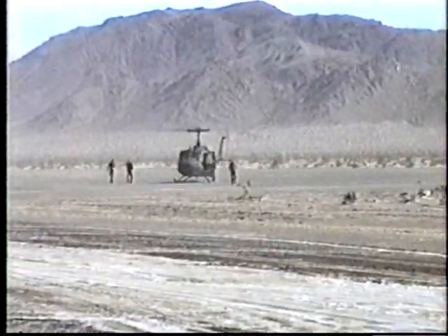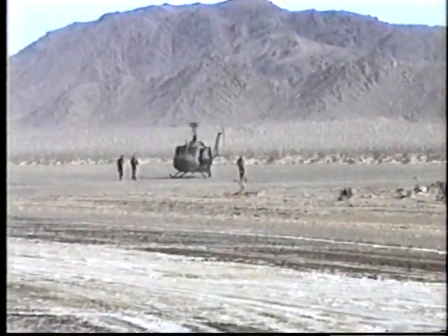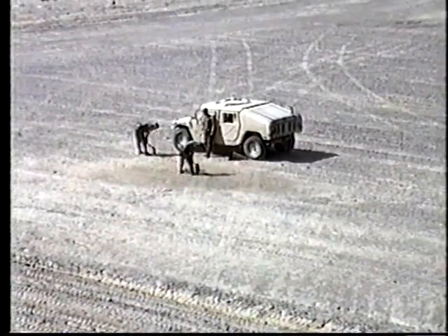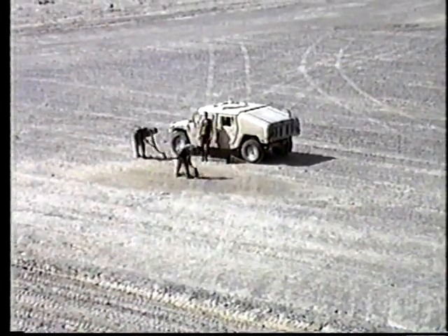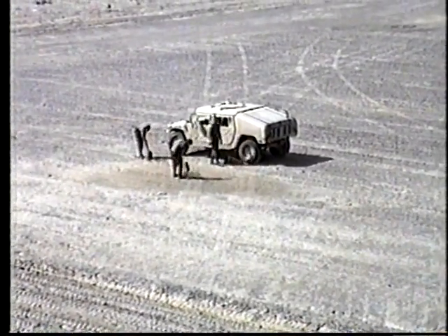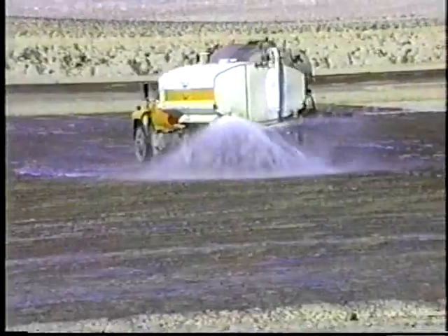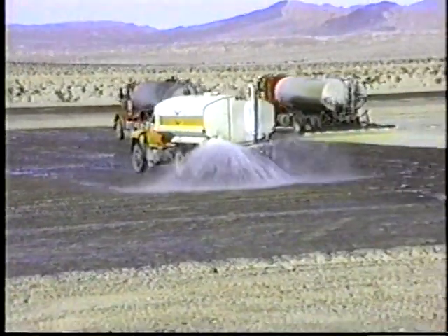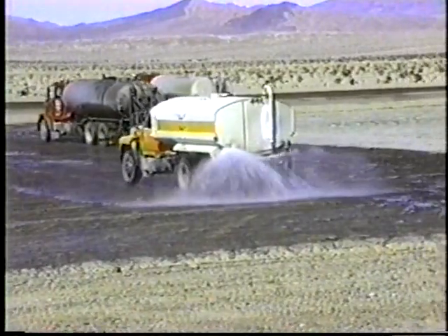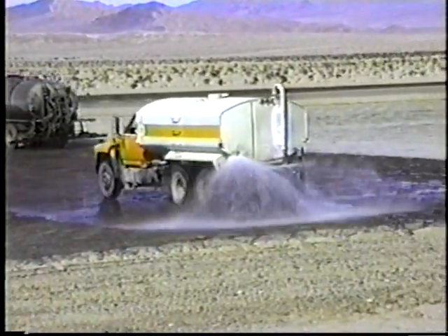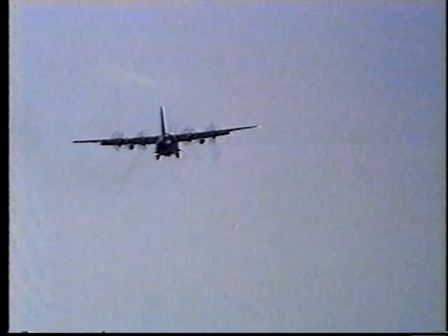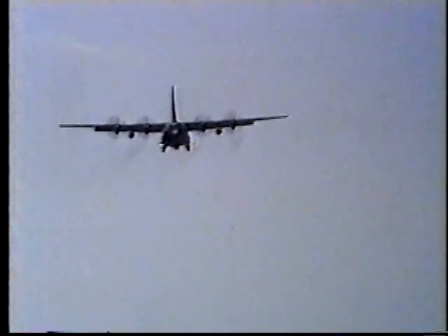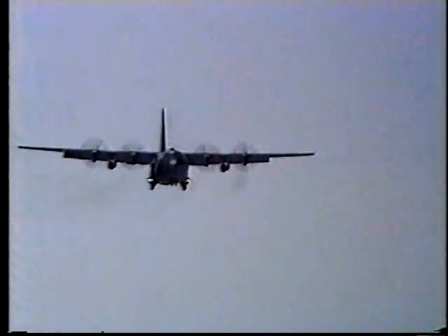Let's take a look at some road oil applications on runways, helipads, and roads. This aggregate surface runway was graded, pre-watered, and then protected by a multi-coat application of road oil. The initial coat was a surface penetration of the untreated aggregate. The following day, a road oil coating was again applied, this time as a surface seal designed to further harden the runway for service under C-130 landings and helicopter touchdowns.